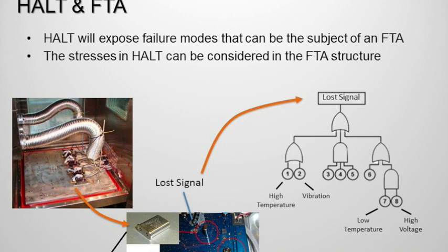So if the objective of HALT primarily is to expose failure modes, it's quite clear to see how this would work very well in conjunction with an FTA. In a traditional HALT, you would expose a failure mode through high stress and begin that process of trying to understand what happened. Well, why not do it in conjunction with the formal FTA process, which includes the whole team and a much broader spectrum of information doing that analysis?